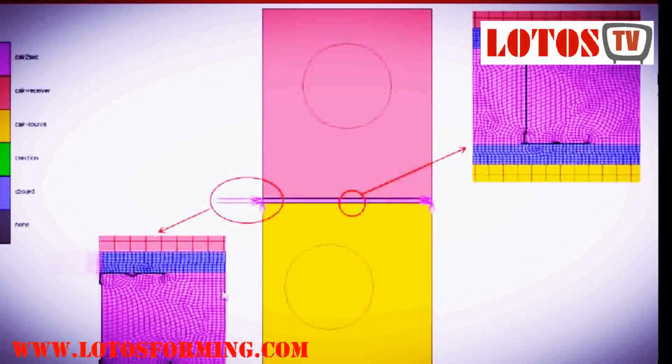This shows the system at the corner. As you can see again here, the stud and the air cavity connect to the stud, and we apply the sound pressure on the wall of the source room, and the two circles you can see here are the areas that we measure the sound pressure magnitudes in the source room and in the receiving room, similar to the one set up in the test.